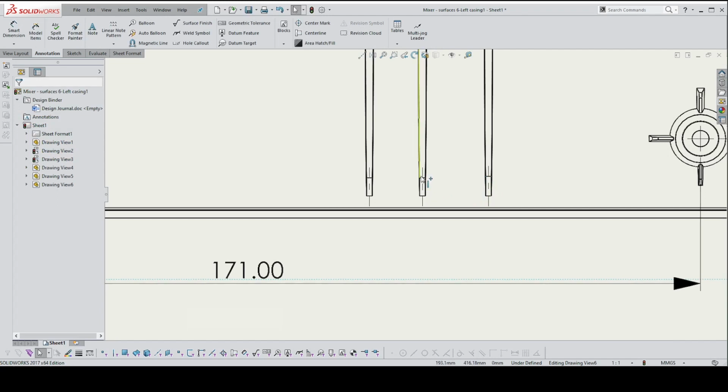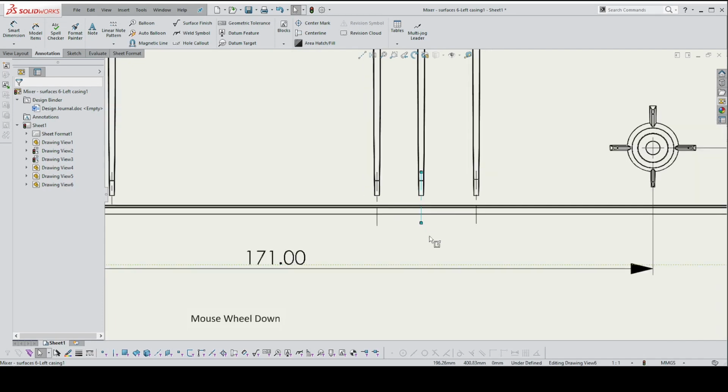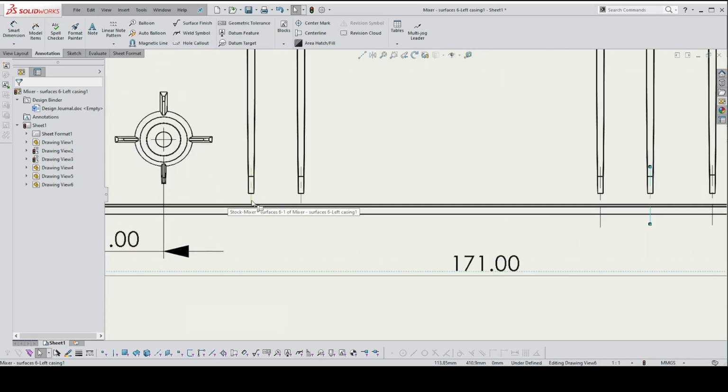Okay, and the reason I'm selecting center lines is because that marks the position of the rib, because the way I created the rib is around a center line. And it's also easier because you only have to dimension one of these ribs as to its root wall thickness once and as to its other features once. So once you've got it, that's not going to pull out. I'm pulling these out just so that they're easier to access when I put in some more position dimensions.